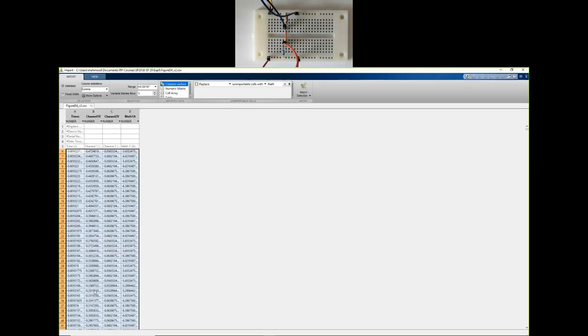It is going to highlight all the data points that I might be interested in, and it asks whether I want to import the data as column vectors, a matrix, a table, or a cell array. I want to import it as a matrix where I can access each column. I could have chosen column vectors as well, but the code that I've already written is suitable for a numeric matrix. So I'm going to select numeric import, and that is fine.